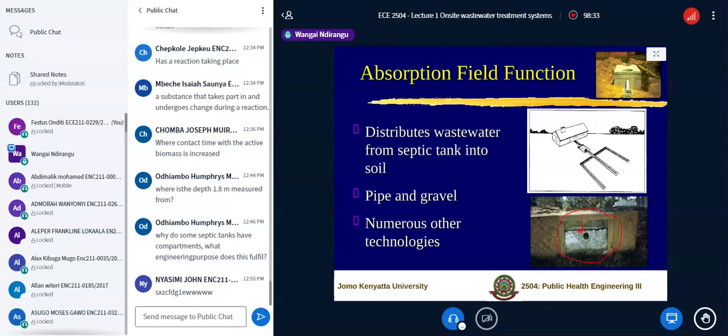You can see that there is this distance here. The distance is sufficient to ensure that there is no physical damage, but also not too deep. In fact, this whole depth is about 0.6 meters, at the very most 0.9 meters. Why do we do that?